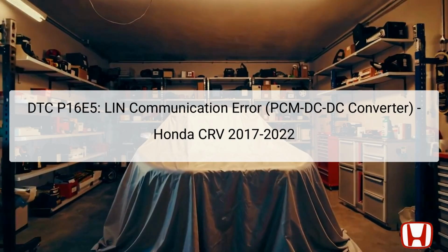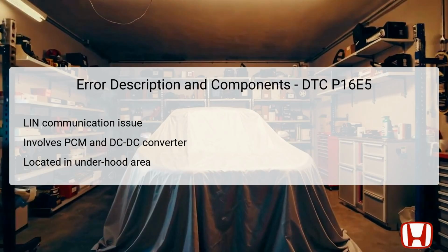system, including the DC-DC converter, which steps down the high voltage from the hybrid battery to a usable voltage for the vehicle's electrical system. This troubleshooting guide will help diagnose the problem by checking various components and connections involved in this circuit, ensuring that they are functioning correctly and are free from any shorts or opens that could cause communication failures. The error P16E5 symbolizes a LIN communication problem, specifically between the Powertrain Control Module, or PCM, and the DC-DC converter located in the engine compartment of the Honda CRV.